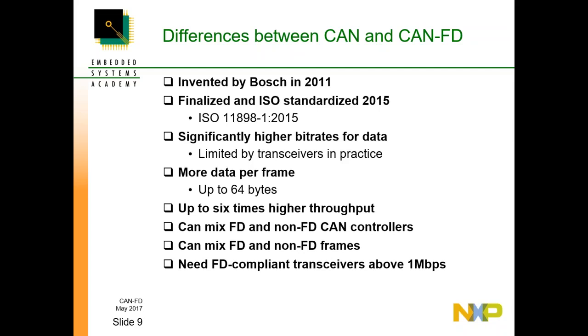The second key difference with CAN-FD is the increased amount of data per CAN message. Classical CAN is limited to 8 bytes, and this can be a challenge for some applications to deal with. For example, in the higher layer protocol CANopen, there are 2 approaches commonly adopted. There is a software protocol that handles fragmenting blocks of data over multiple messages, and there is a desire to try and keep data objects less than 8 bytes in size in these protocols to avoid having the hassle of fragmentation handling. With CAN-FD, the limit is increased 8-fold to 64 bytes per message.